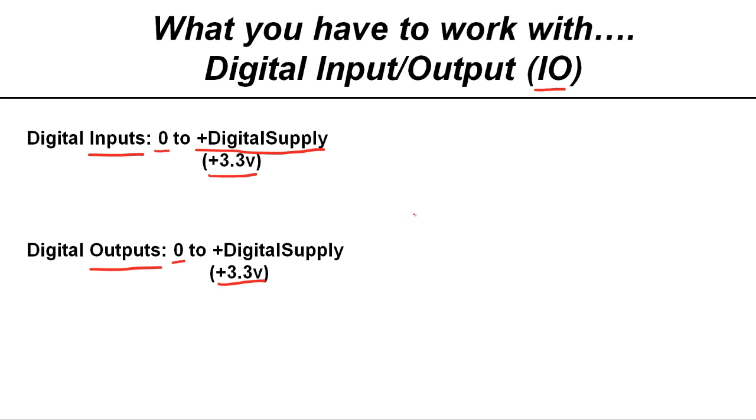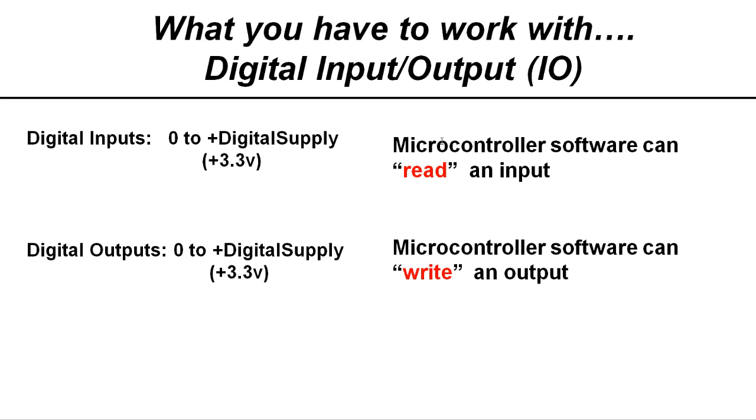And by using software, we can have a digital I/O turn on an output or turn it off. And by playing around with the software, we can create special timings. We can make little pulses. We can almost do whatever we want. Our only limitation here is that the microcontroller takes a finite amount of time to read an input or control an output. So, always think about this.